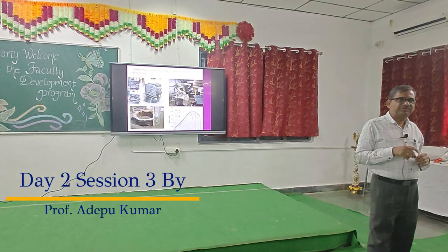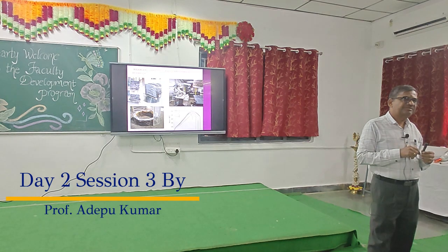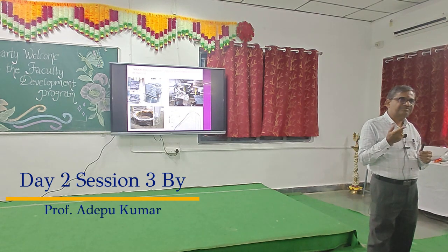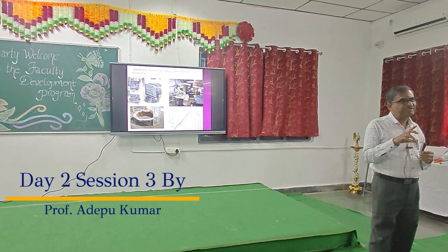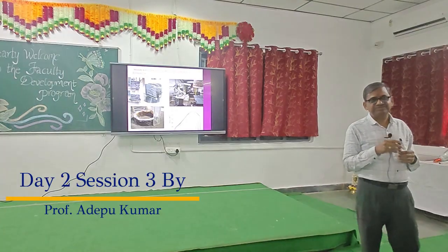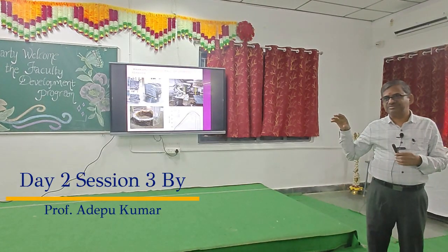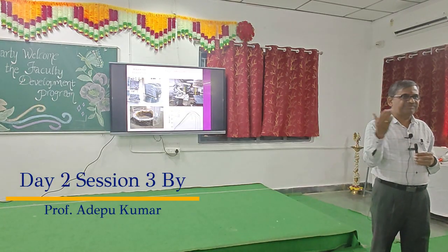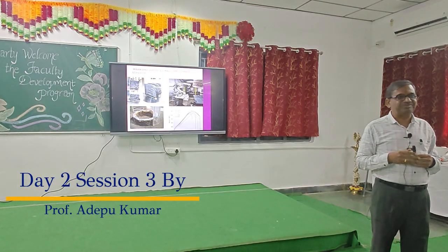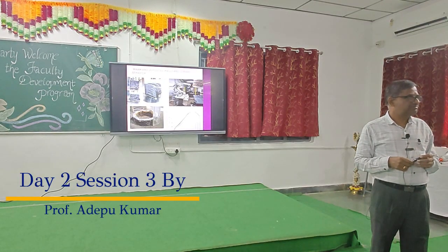So once you are using the technology of retractive feeding with milliseconds, the arc is not initiated, and when the arc is not initiated, heat is not generated, so the amount of heat accumulation is less compared to the old technology. So you can reduce the amount of distortion. So you can weld even 1 mm, even 0.1 mm also you can weld. That technology is used in Maruti and other automobile companies.